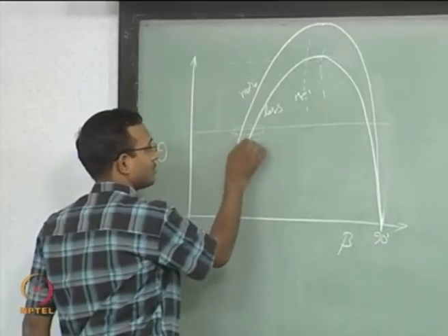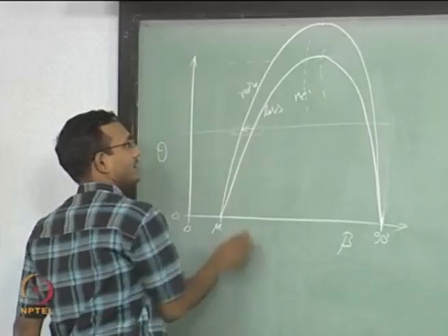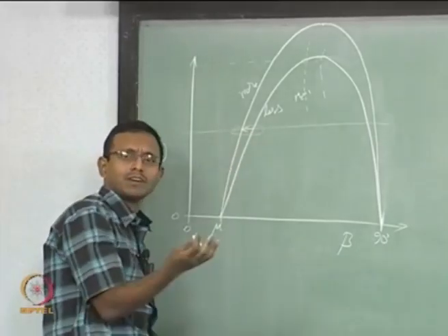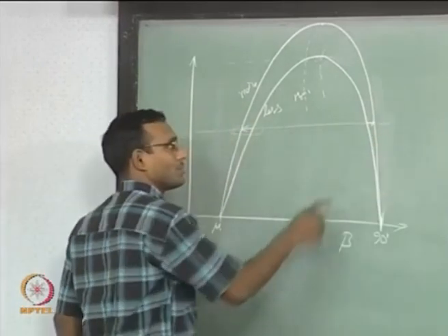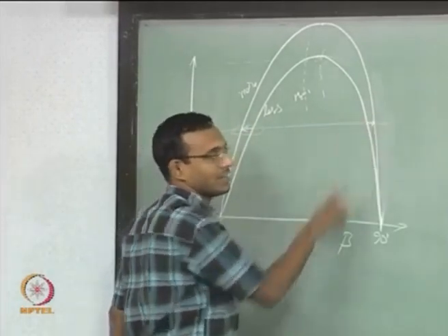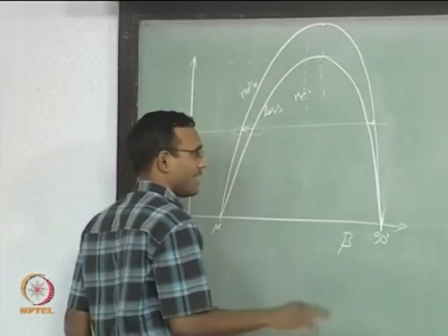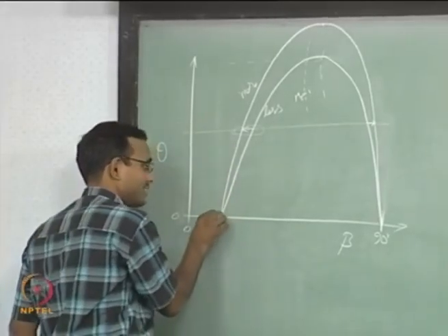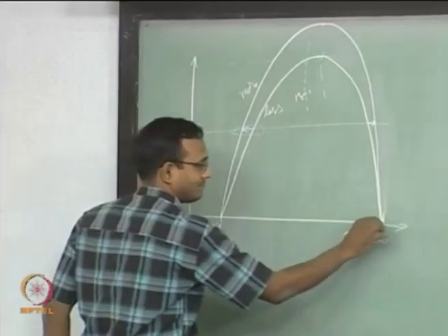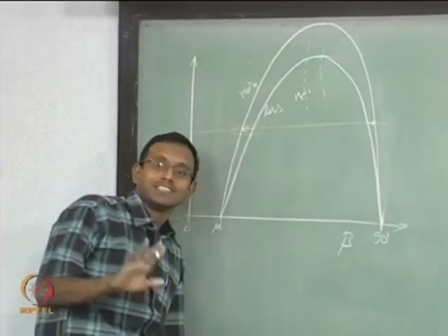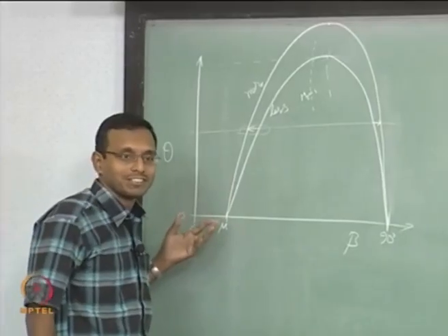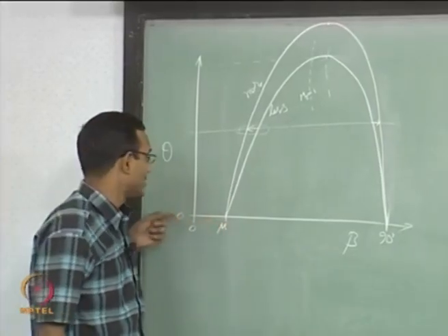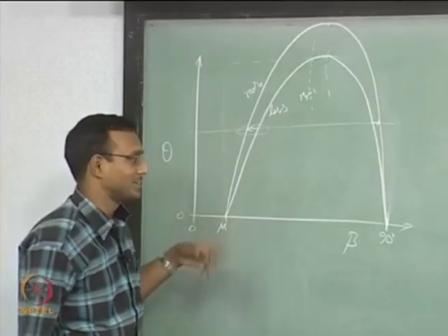Okay. If it is a weak shock solution, we find that beta decreases, we proved it. Okay. If it is a strong shock solution, we proved that as it becomes more compressible, it goes that way, beta increases. Okay. And you notice that there is no change at 0 deflection, okay. There is no change at 0 deflection. Of course, if it is mu, there is no shock, it is a 0 strength shock, okay. So it just goes through straight, there need not be any deflection.